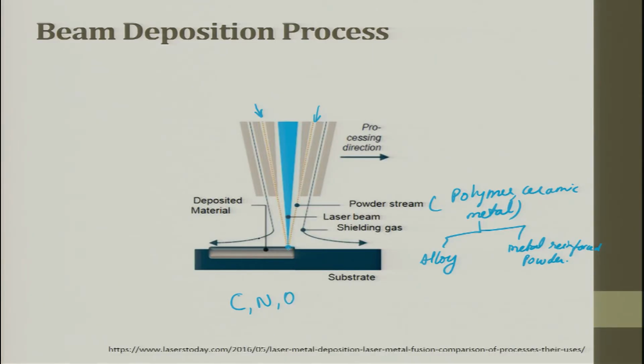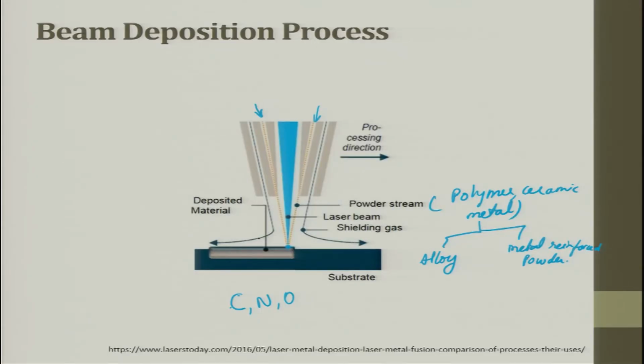The powder in the molten condition, where diffusion can happen very fast, can form carbides or it can form a ceramic material on top of it, which might functionally degrade or deteriorate the usage of this part in real time. So, whatever gets generated from here is directly used as a final product for usage.